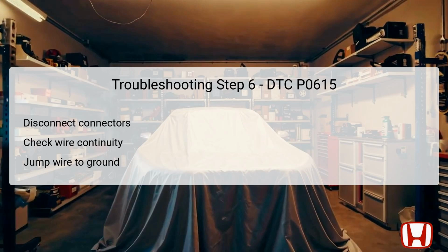In this step of the troubleshooting procedure, the focus narrows to the IG1 ACG line. Disconnect the necessary connectors, including the under-dash fuse relay box connector C and relay circuit board connector B. This disconnection allows you to safely check for continuity within the circuit without cross-interferences. Next, to verify functionality, connect terminals A and B with a jumper wire, linking terminal A from connector C to the body ground. This action sets up the parameters for a continuity test.